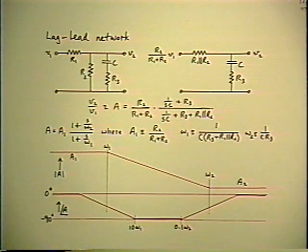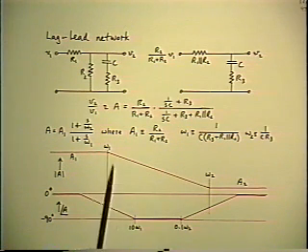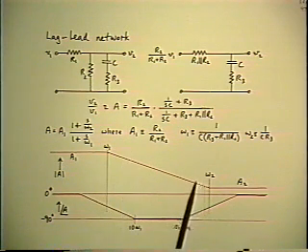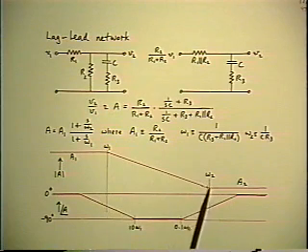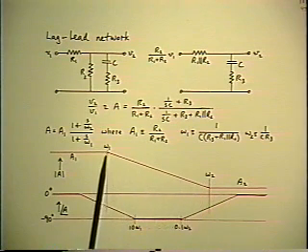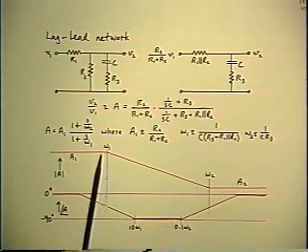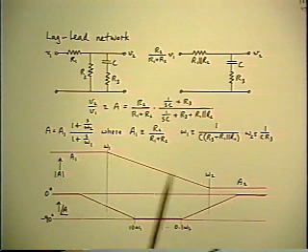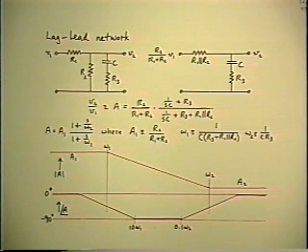Now, that's actually pretty obvious because this slope, after all, is 1 for 1. It's simply a reciprocal function of frequency. That was its origin, which we already did. So it follows directly from that even, that the ratio of the two flat gains is the same as the ratio of the corner frequencies. But it's a very simple thing and very useful.